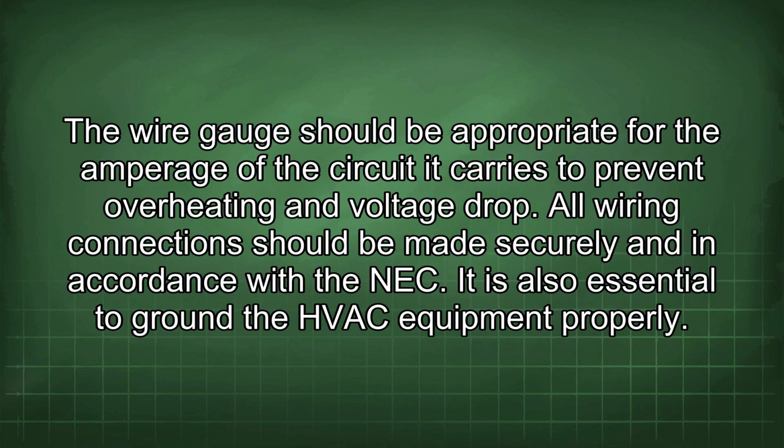The wire gauge should be appropriate for the amperage of the circuit it carries to prevent overheating and voltage drop. All wiring connections should be made securely and in accordance with the NEC.